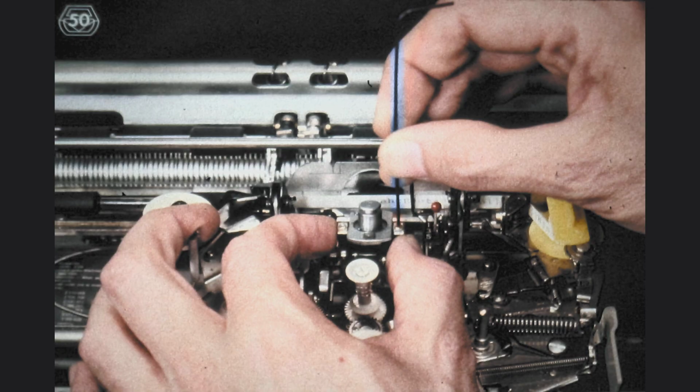Having properly lubricated the tilt ring and the lower ball socket, we can reinstall the ring. The tilt ring is reinstalled by applying finger pressure to the pivot studs which hold it in place.